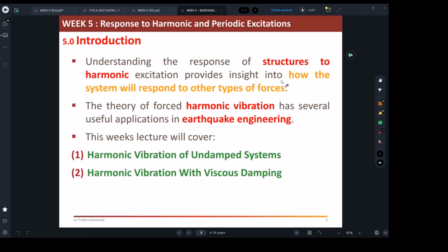Maybe the council will intentionally say to you, I don't want you to push that structure because you don't know how weak it is. If we're talking about heritage structures, maybe they're very brittle. You cannot really push it by 20 millimeters or 15 or 10. You may break it.